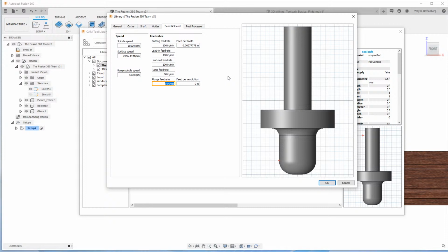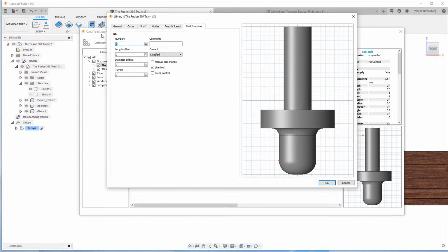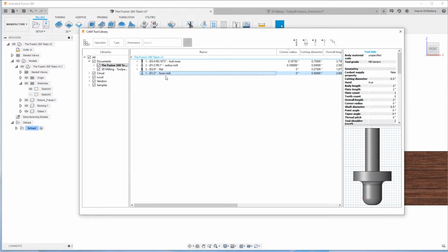It really depends on what you're trying to cut, what types of materials you're cutting, the material of a tool and so forth. So have your specific feeds and speeds that make sense for the job you're doing. This will be tool number 1 for this job, and I can also put in our air blast, or if we don't need coolant, I'm just going to use my vacuum to suck up the chips. Right? So we went through the library like we were creating a brand new tool.